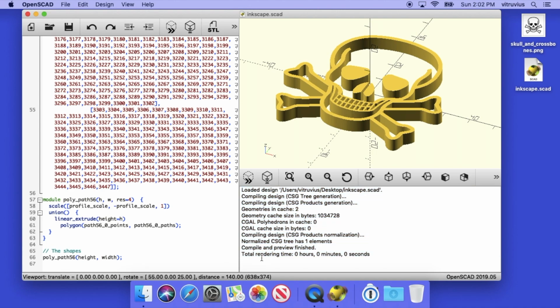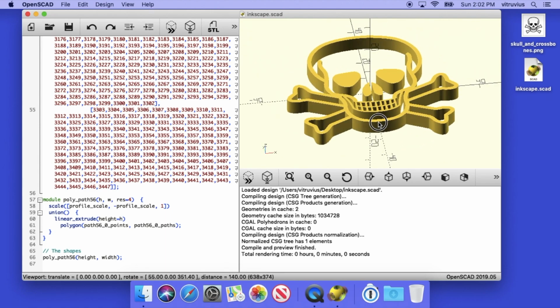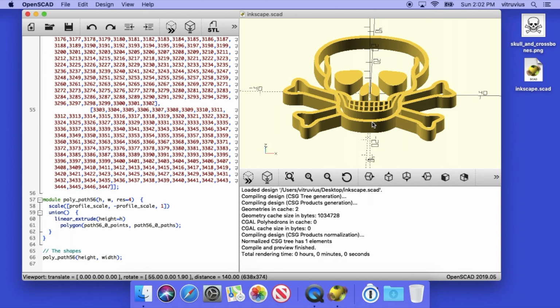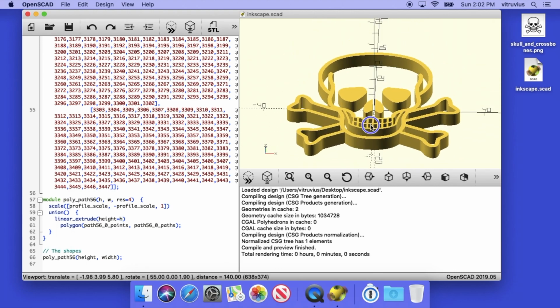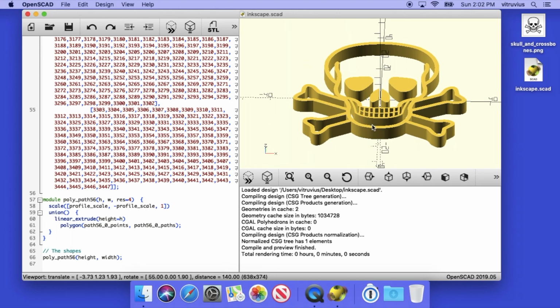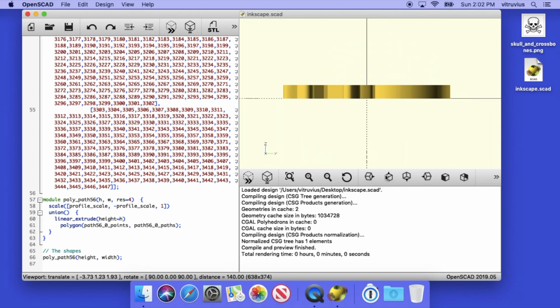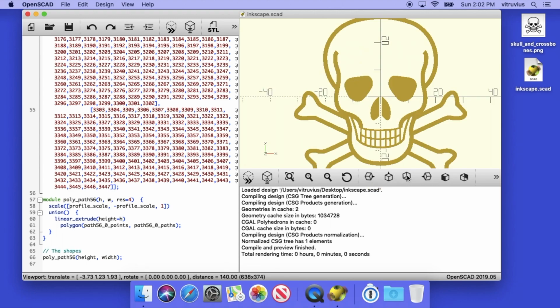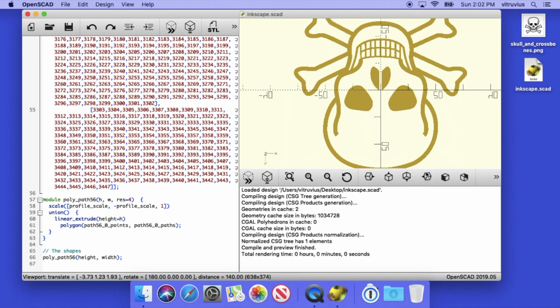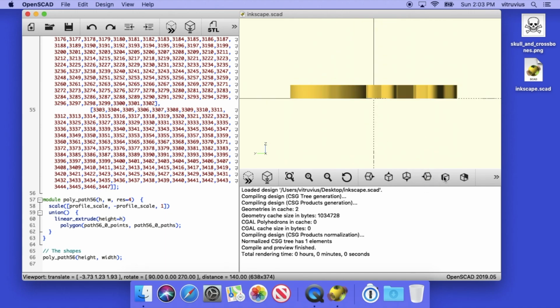And there are a variety of ways that you can manipulate the image in that window. You can click your cursor and drag it left and right or up and down, and that'll rotate the object. Or you can hold down the Control key while you're doing that and move the entire image up or down or left or right. And then there are some presets along the bottom of the window that allow you to set views explicitly. So there's from the right, or from the top, or from the bottom looking up, or from the left-hand side, and then from the front and from the back.